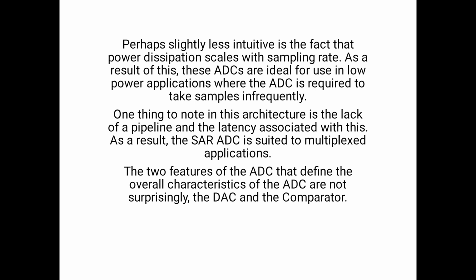Perhaps slightly less intuitive is the fact that power dissipation scales with the sampling rate. As a result of this, these ADCs are ideal for use in low power applications where the ADC is required to take samples infrequently. One thing to note in this architecture is the lack of pipeline and the latency associated with this as a result. This SAR ADC is suitable for multiplexed applications.